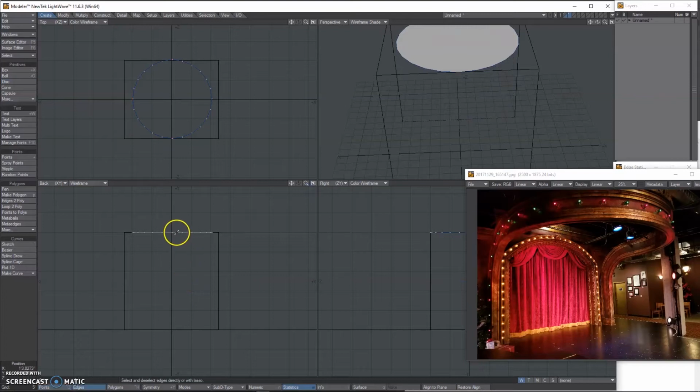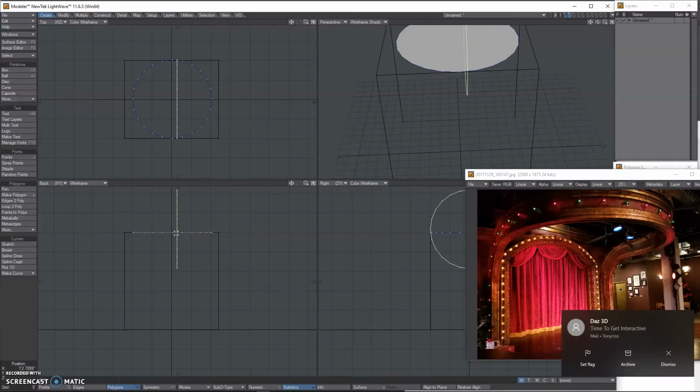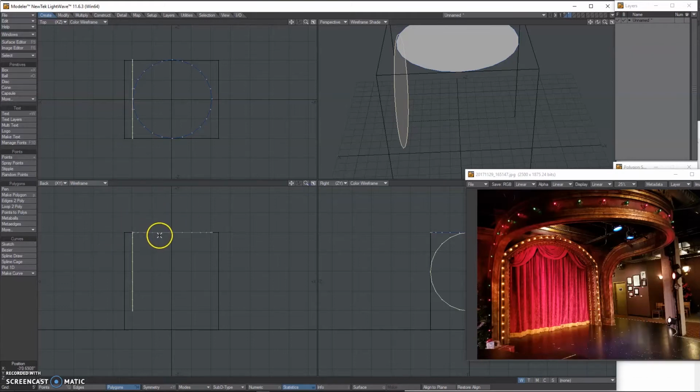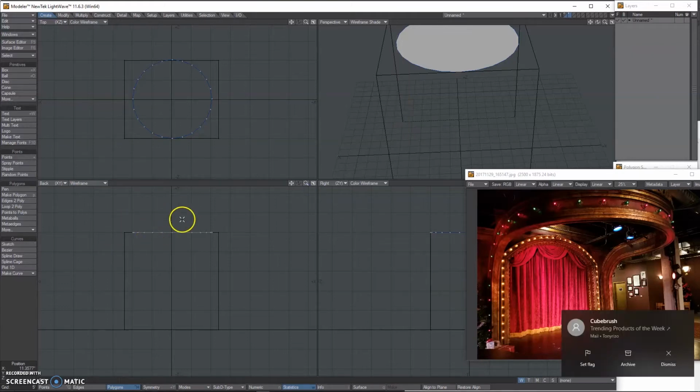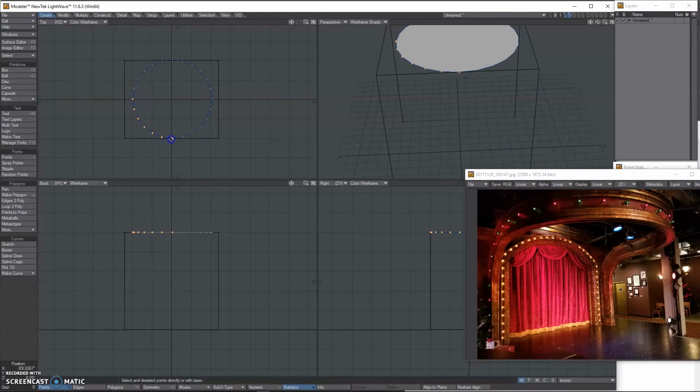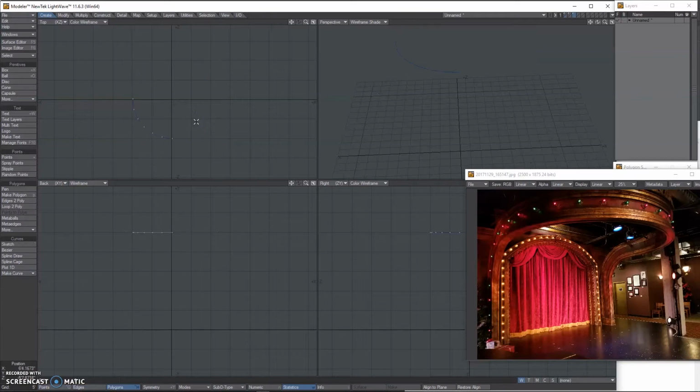And then the other thing we're going to do is I'm going to select it, copy it, paste, hit R for rotate, and this is going to be my side. I'm going to hide that by using the minus key, and I'm going to make a spline. So I'm just going to grab these points, Control P, makes a spline, cut that out, go to my third layer, just paste it in, go back to 2, hide this one.